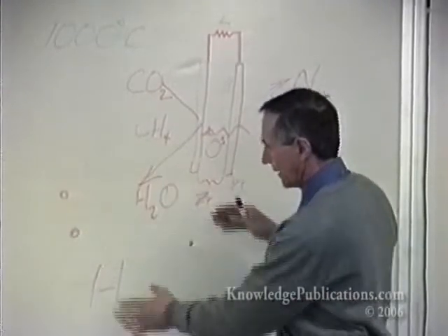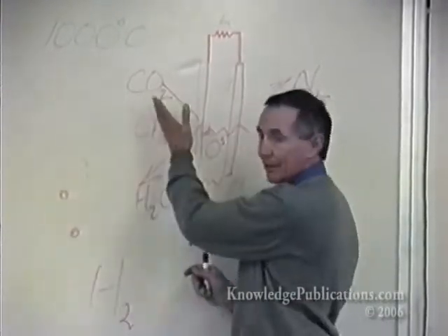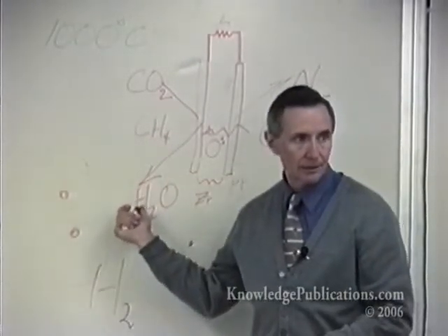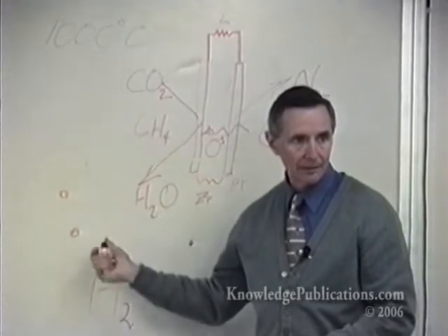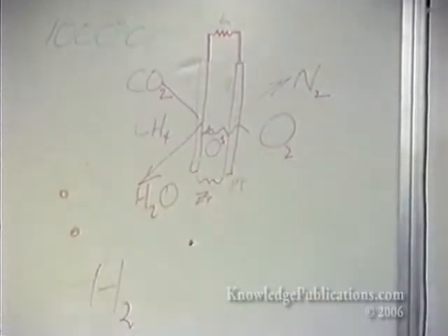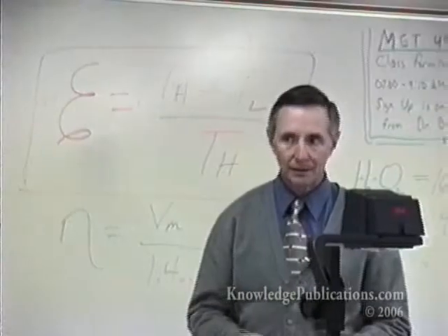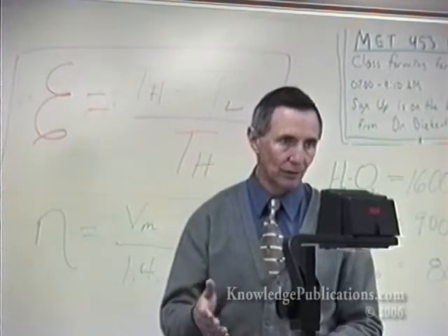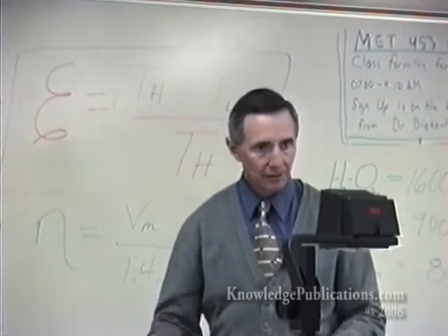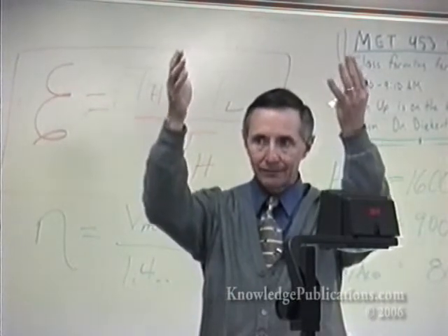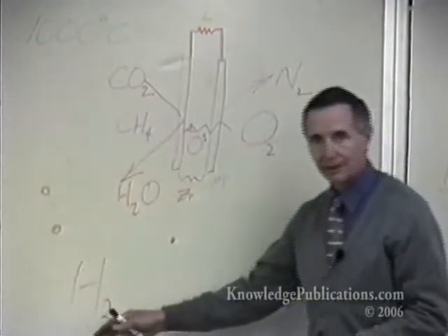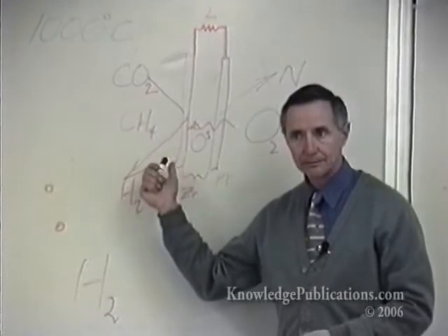If you're at the other extreme, this being the PEM, if you're up here with a high temperature cell, such as this zirconia, solid oxide membrane, then you also need to incur the cost of heating it up and operating it at a high temperature. You still have that activation going into the fuel, which started at room temperature. Now you use heat to bring it up to temperature to make it reactive. So it's consuming energy one place or another, either in voltage at low temperature or in heat units at high temperature.